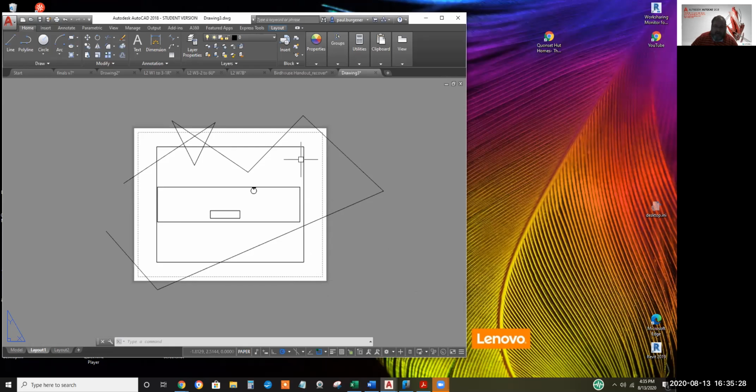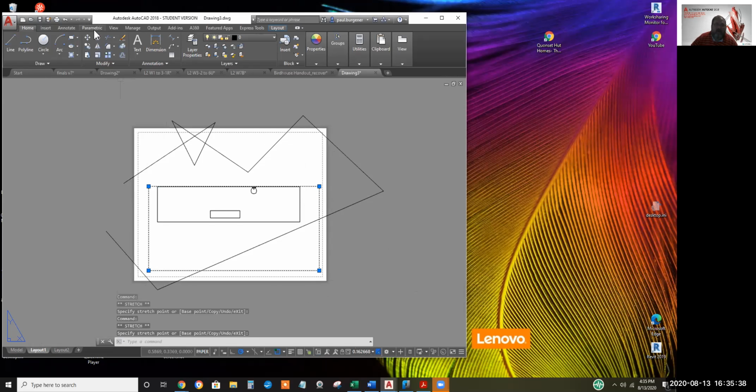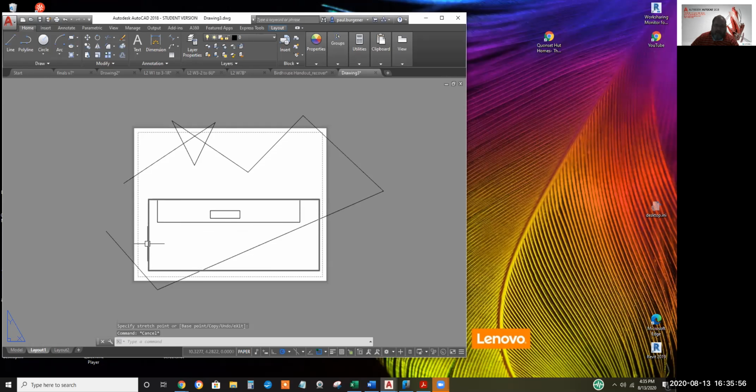A nice, neat thing about these viewports is you can grip edit them easily. Short of the parametric stuff, which I've yet to teach, I think viewports are the only shape that remains rectangular as you grip edit it. So I just reduced the size of the window that we're looking through by grip editing the window in the front of the Burger King.